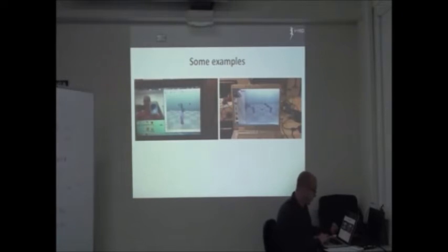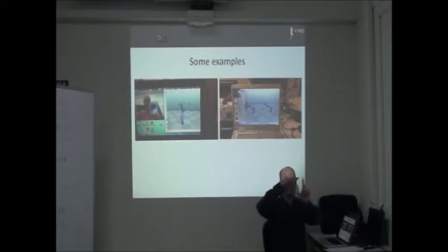Another example of input: I have in my hand an augmented reality tag, which is a mark, like a square with some detail in it, that is recognized by the camera. The algorithm is filtering the image. It knows the patterns that it needs to see, so by the deformation of it, you can extract the position and orientation in space of the tag in the camera frame.